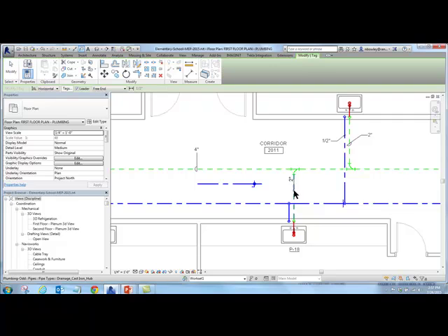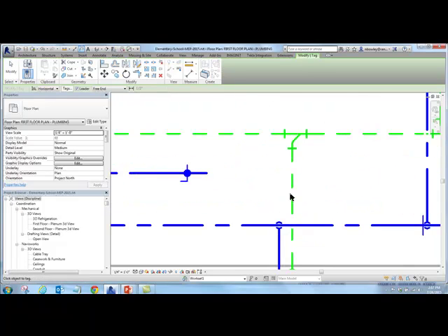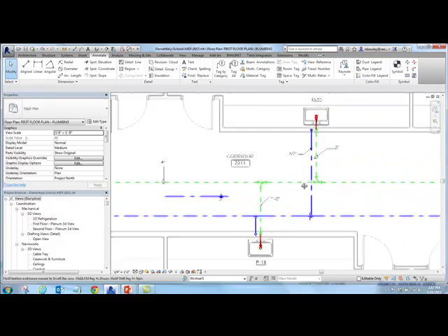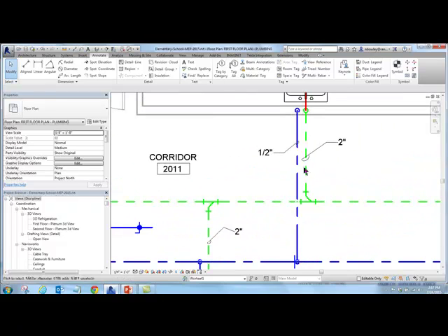So I'm coming in here, I'm trying to tag this pipe here, but my tag is set to align, so the tag is rotating with it. Pull it off to the side, and I try to put in this nice flat landing, and then it rotates, and then my landing's messed up. So again, this might seem simple, but some people it might drive crazy. They may not have figured this trick out yet.